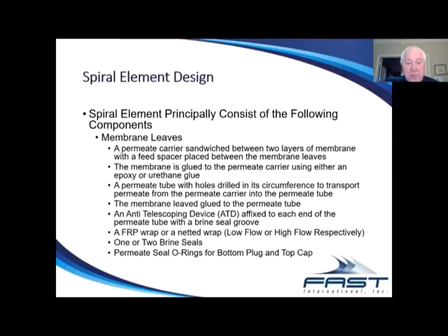One is with fiberglass reinforced plastic that is wrapped around it, or a netted wrap. Those are often referred to as low flows or high flows, respectively. And then on the ATDs, there's either one or two brine seals, and there are usually permeate O-ring seals supplied to replace the ones that are currently in the top cap and bottom plug.